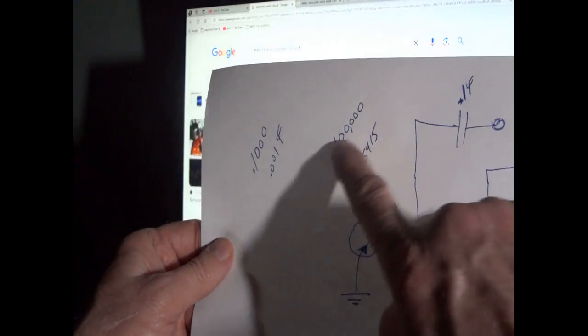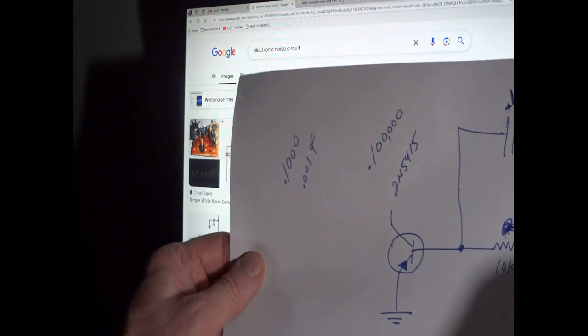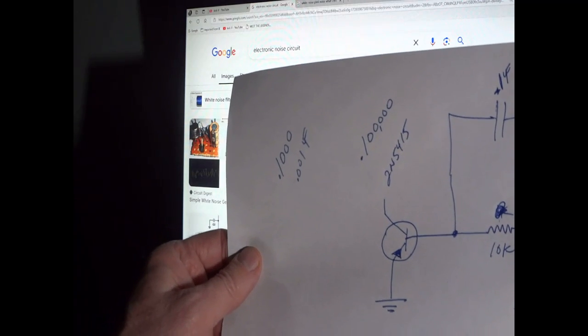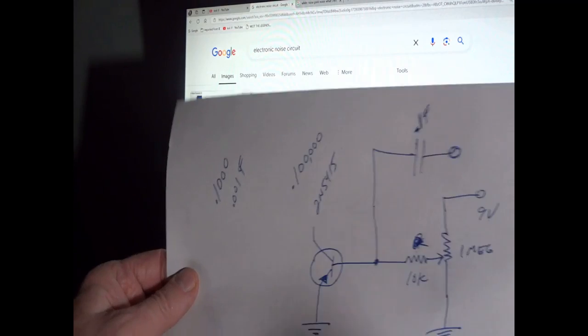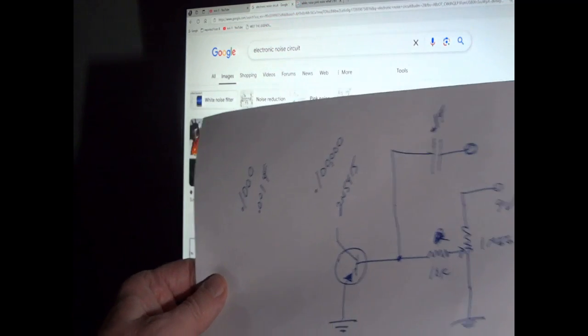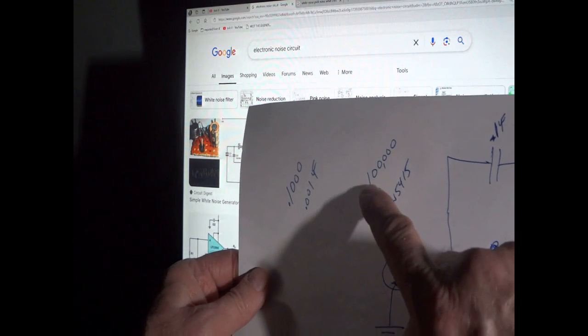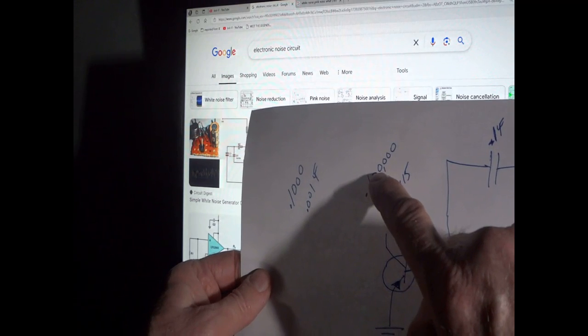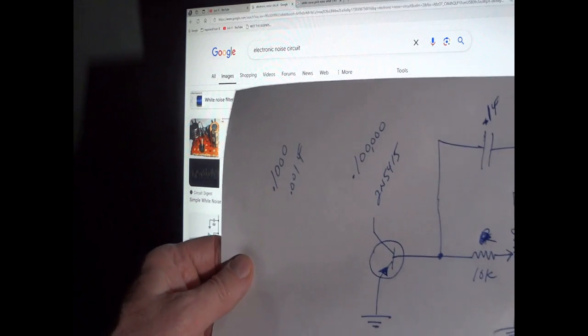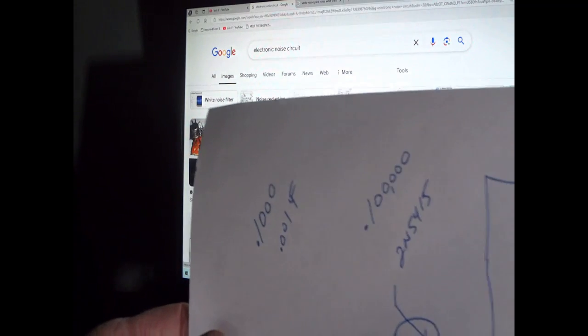And then with the capacitor here, we're just doing some math, figuring out what capacitance it was. It turns out to be a 0.1 uF. What's written on it, I believe, is a 104. So you put down a 1 and a 0, and then you add 4 zeros, and then you read it in picofarads. That's how you read those capacitors with those numbers on them.